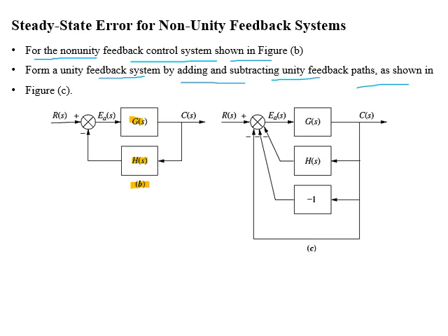Students, here we are converting our system into a negative feedback system. So the branch with a gain of +1 will be added such that its gain will be -1, and its algebraic sign at the summing junction will be negative. So minus into minus will be positive, and our overall system will be a negative feedback system, as shown in figure C.